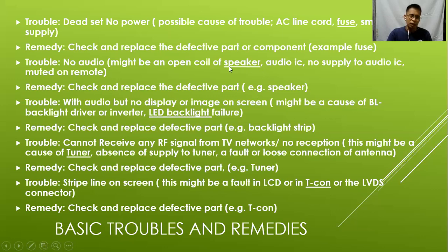So I underlined speaker, because that is the cause of trouble, no audio. So for example only, speaker. So what will I do? For the remedy, check. And then after checking, I found out that the speaker is already defective or busted or not working. So I will replace the defective part. What is the defective part? Speaker. So my remedy is check the speaker and replace the speaker.